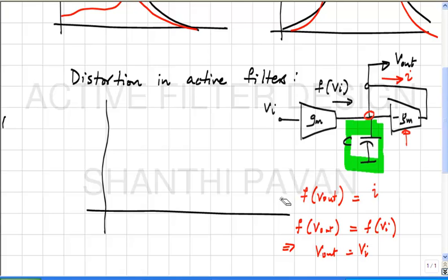So roughly a good tone test is to put, so if I typically plot the third harmonic distortion, which is the amplitude of the third harmonic at the output divided by the fundamental at the output. Yes, if the passband gain is 1, then the fundamental at the input and the fundamental at the output will be the same amplitude, right? You will find that at DC it's very low. Let's say this is omega naught, this is the band edge, right? And then it kind of peaks and kind of falls off again. This will roughly happen around omega naught by 3.